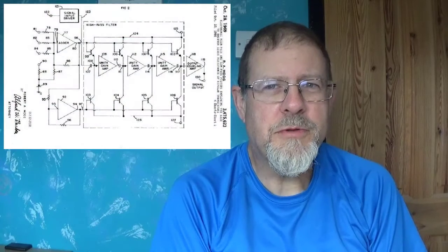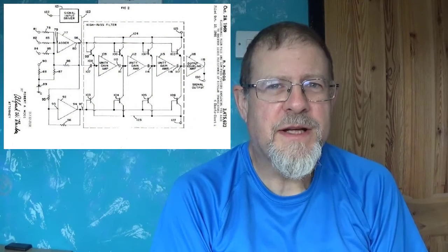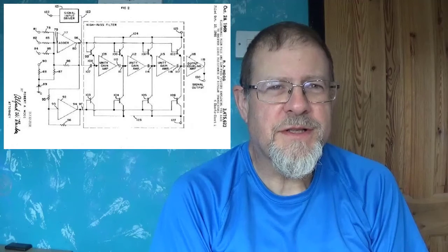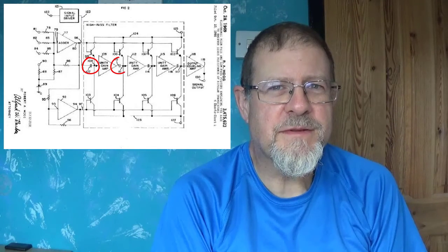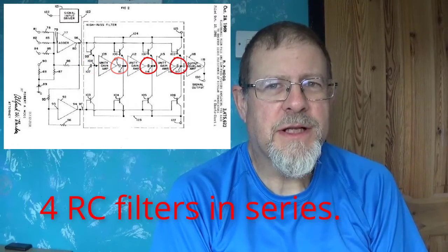In the first part of these filter enhancements we tried to make our filter sound a bit warmer, with limited success. So let's try again, only this time we are going to use a 4-pole low-pass filter of the type used in a lot of analog synthesizers such as the Moog. This is Bob Moog's original patent, and you can see although he's using these transistors as resistors, there are 4 capacitors, so it's 4 filters. Let's have a look at how this 4-pole filter works.